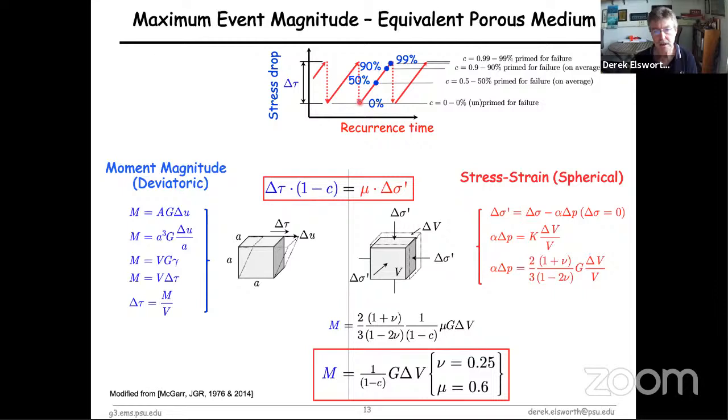The idea is, if you look at the seismic cycle, stress builds up from tectonic forces over time. It reaches a peak, and when it exceeds the strength, an earthquake or a seismic rupture occurs. You drop the stress down to some stress drop magnitude, and then the cycle begins again. And so it matters where on this trajectory you are when you trigger it with the injection of fluid. If you think about triggering it when you're almost close to it failing, you can imagine that you don't have to inject very much fluid to be able to move it up an extra 1% to get it to fail.